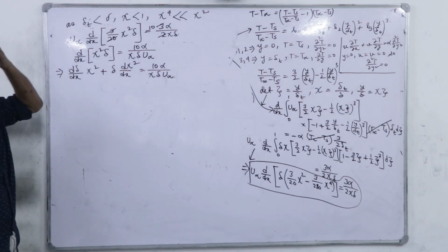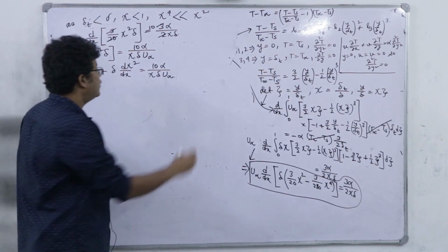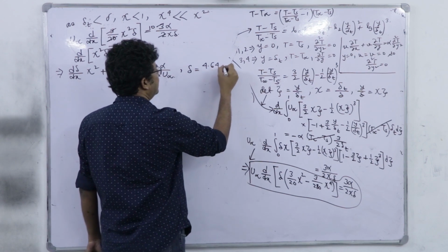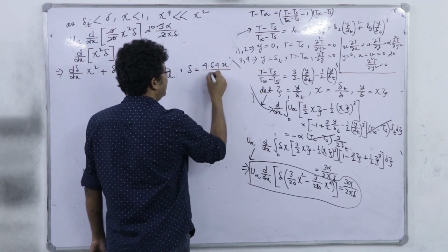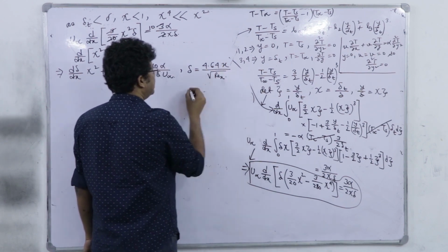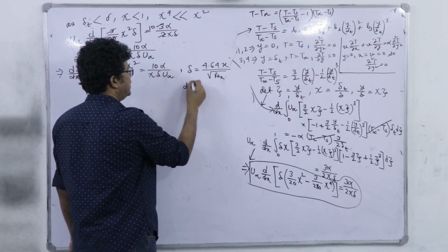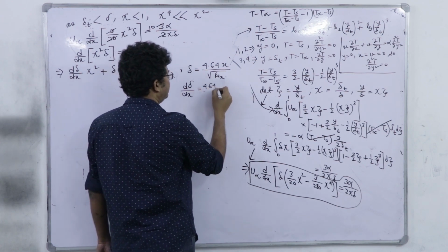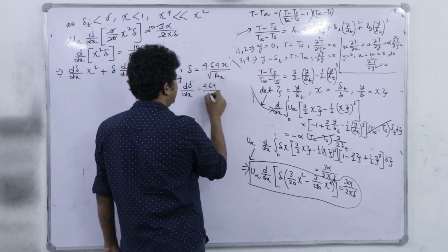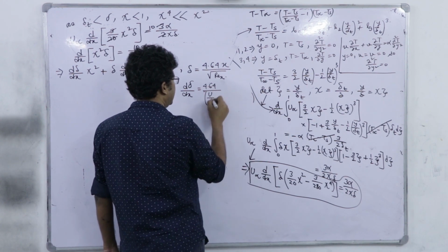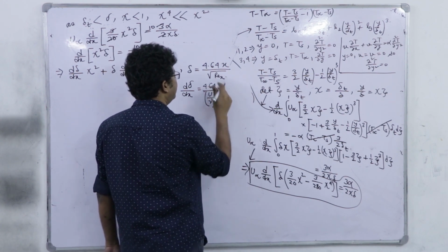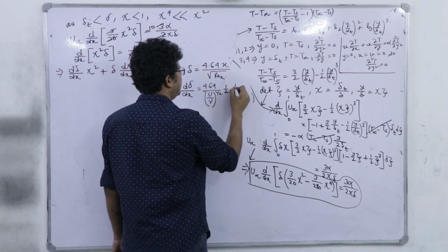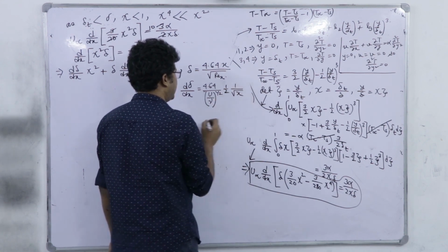Got it? So, you see this Blasius solution gives delta equal to 4.64 into x divided by under root Rex, right. So, d delta/dx is equal to 4.64, and actually here Rex, if I break it down, is (u by nu) to the power half, and this is x to the power half. So, half into 1 divided by under root x.